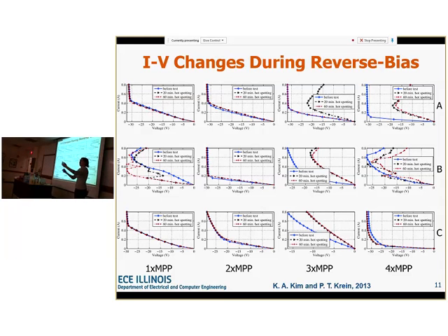Any other questions? Roy? That's back there. Can you avoid hot spotting with something like differential power processing or a cascaded DC to DC converter? Right. So with differential power processing, we're still working in strings. If we went differential power processing all the way to the cell level, or if you did any sort of control at the cell level, yeah, no problem. But it's when we put them in strings that you have the potential for this. The shorter the string, the less potential there is.